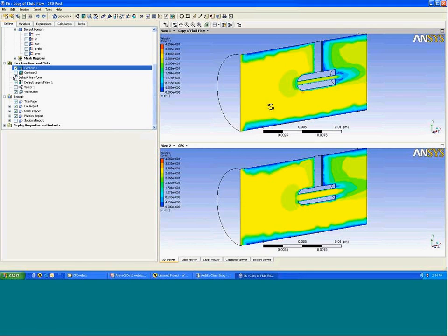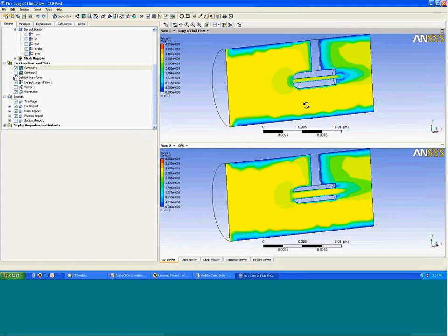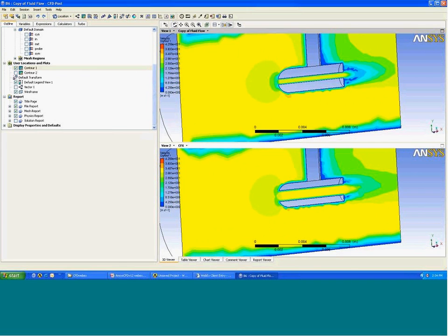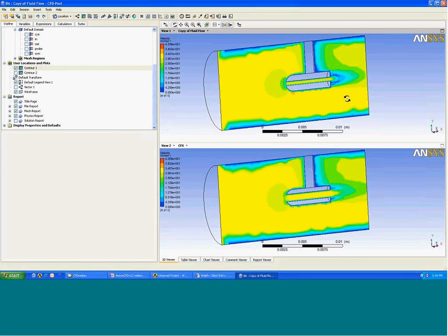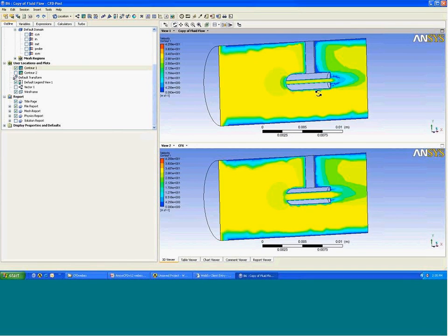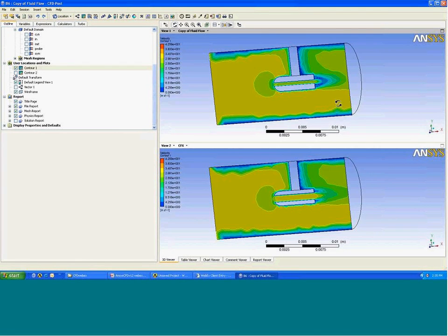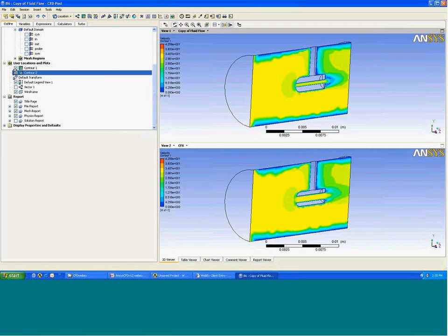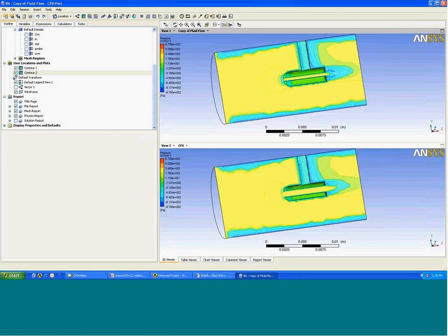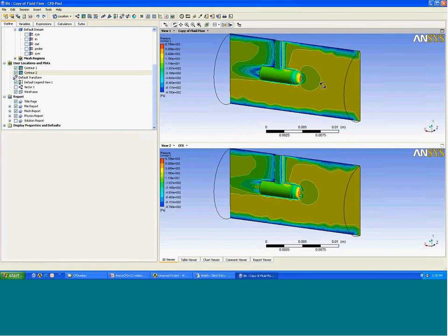By doing that, you can easily compare the flow solution differences between the first design and the second design, and focus on the region of interest to pick out the best solution between these designs. And you can do 3 or 4 in sequence, bring the solutions into CFD Post and compare the differences. So that shows you the graphics, the velocity contour, and the pressure contour on the probe surfaces.